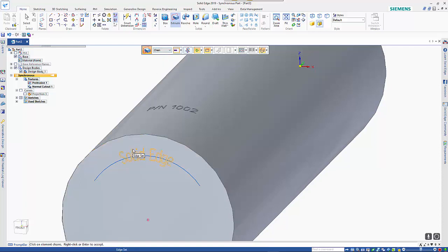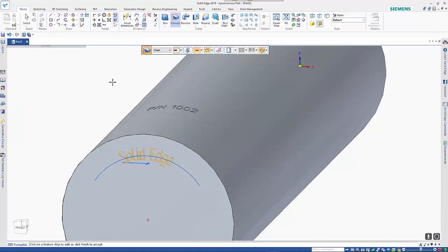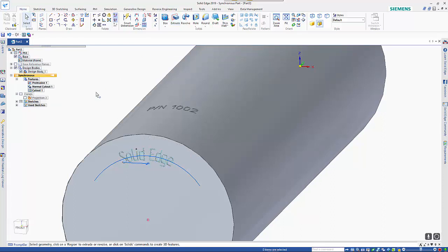It allows me to pick up that sketch that we've created with the text profile, and I'm going to change my option here to cut. I could project it out if I wanted to, but we just need to specify our depth in here to give us that cutout. So again, I can turn off those sketches